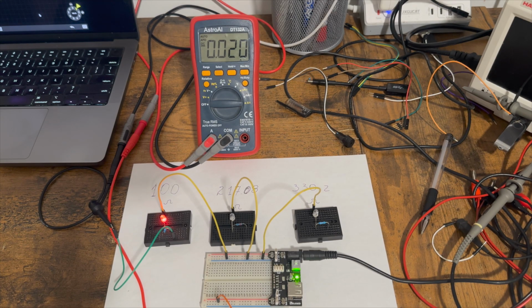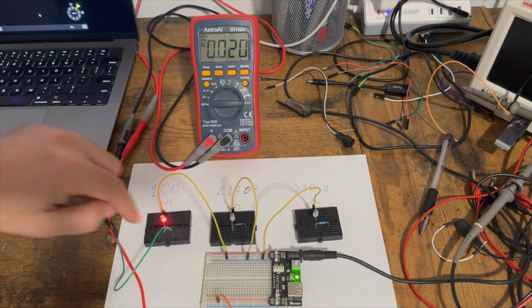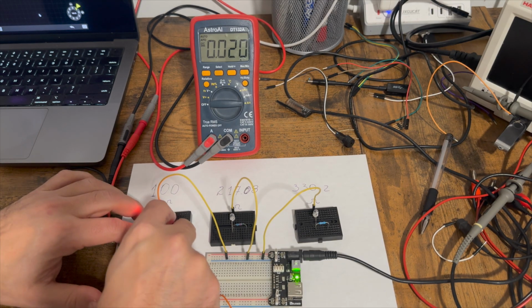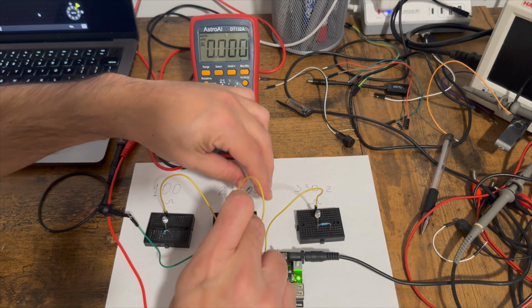But you have to keep in mind that LEDs, although they are very similar regarding voltage forward, might vary among different manufacturers. So putting 20 milliamps at the limit here might be okay to use with some LEDs, but it might not be so good to use with other ones. They might have a different voltage forward. So being at the limit here is not actually very good, but this is what this is drawing for this specific LED. So let's go to the next one.